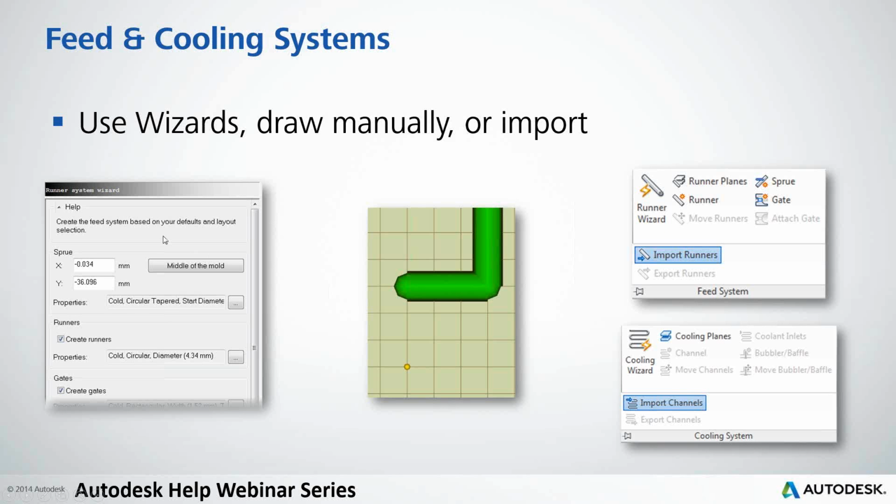To import either of these, you'll have to have the IGES curves from your CAD program. Basically, the center lines on your CAD model, export those as IGES, and you'll be able to import those into Moldflow. If you have trouble, you might have to switch a couple settings within your CAD program, but typically they should come in without any issues.